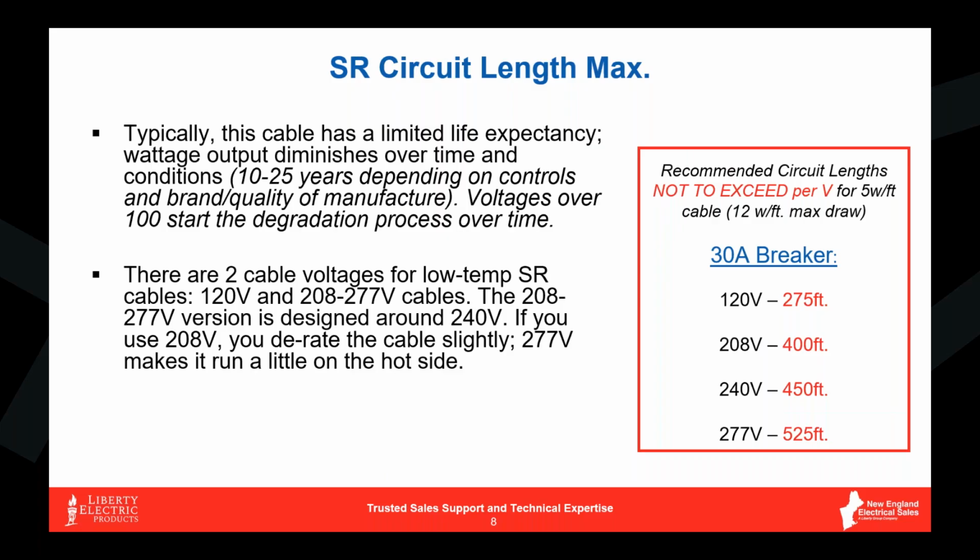And the most confusing part about heat tracing, in my opinion, is generally just sizing the circuits, knowing how much heat cable you can put on each one of those feeder circuits you're bringing out to your job. Obviously, we know that breaker sizes can range from a 15 amp breaker, a 20 amp breaker, a 30 amp breaker. When we do our calculations, we are basing everything off of 30 amp breakers, because we're looking for the most amount of cable we can fit on that circuit.